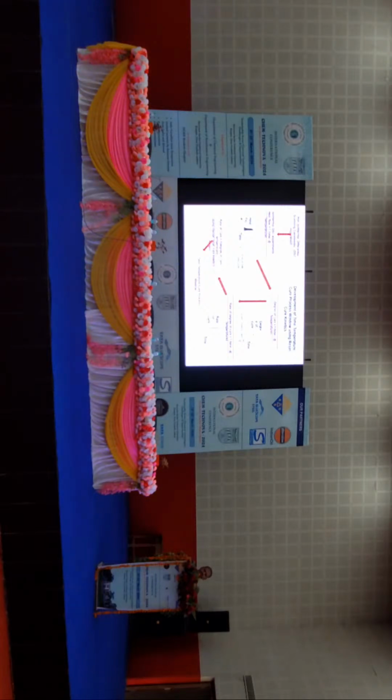So I have to select what my isothermal temperature for curing is. At least 3 temperatures I should identify. How can I identify them? From the non-isothermal study, I get the onset temperature of curing and the cure peak temperature. In between, I have to select 3 different temperatures which can be kept for a prolonged time. You keep the sample in the DSC at the 3 different isothermal temperatures for a prolonged time. If curing is at say 120 degrees centigrade for 2 hours, I have to select, like, 100 degrees centigrade for 3 hours.